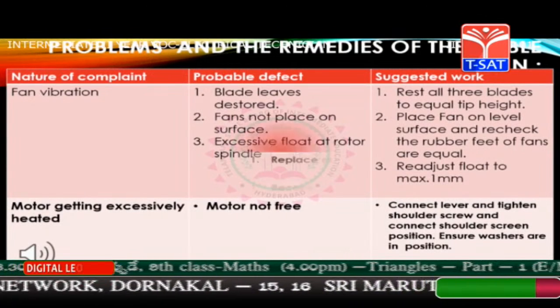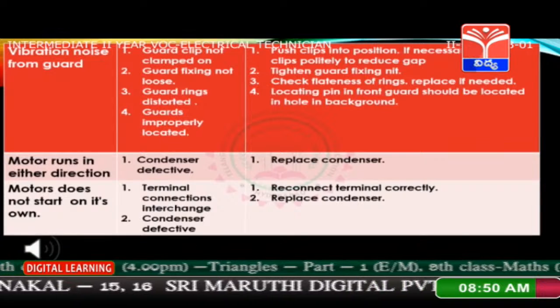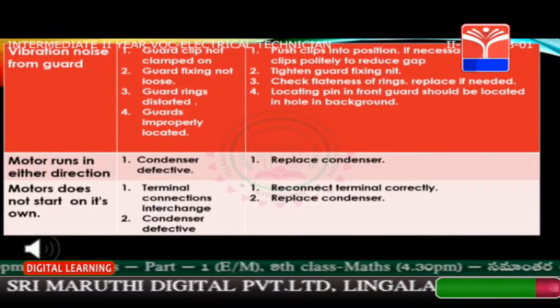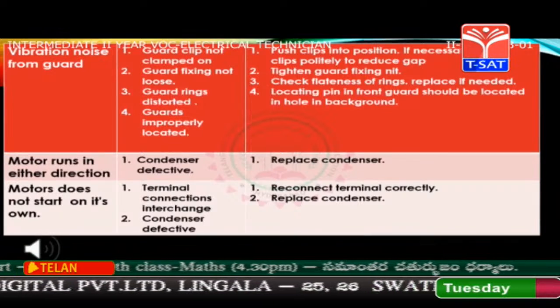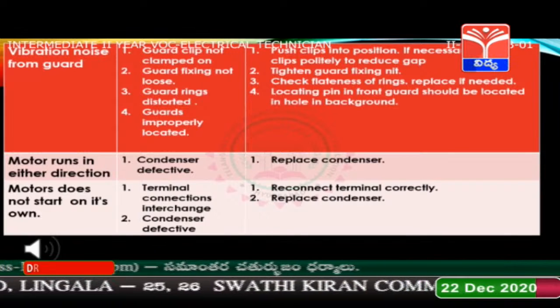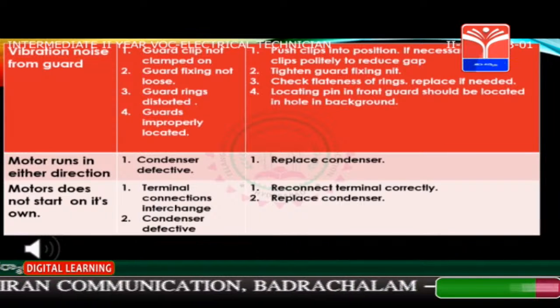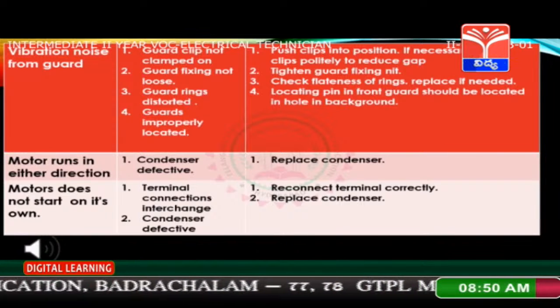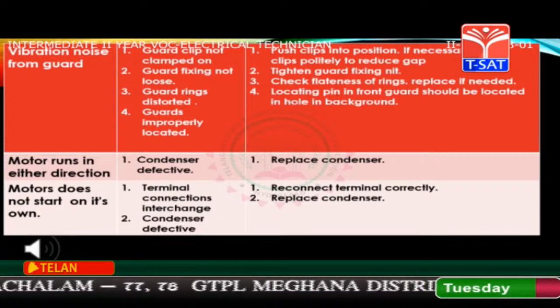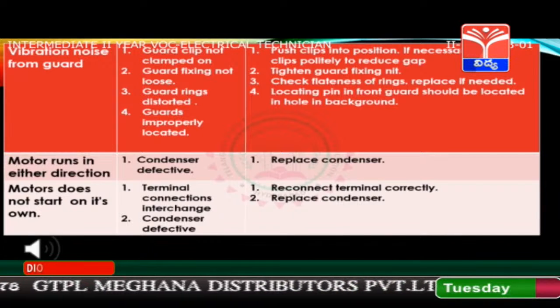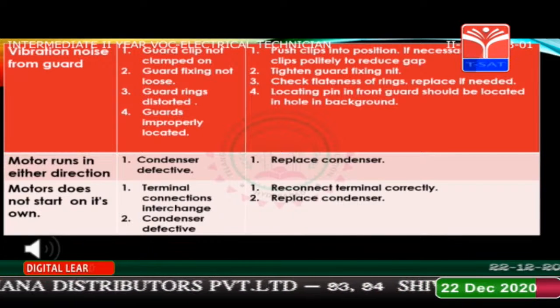Vibration noise from guards. Guard clip not clamped. Push clips into position. If necessary, press clips slightly to reduce gap. Reason: guard fixing nut loose. Remedy: tighten guard fixing nut.